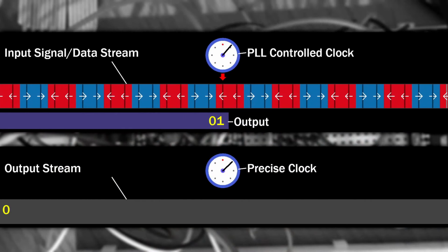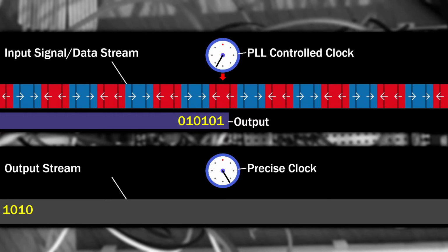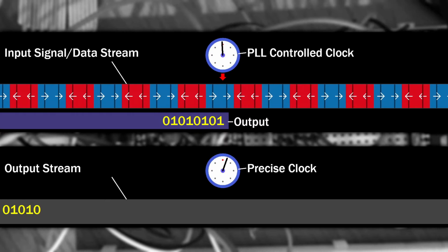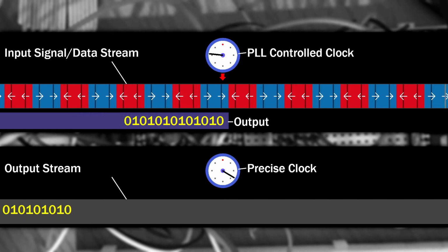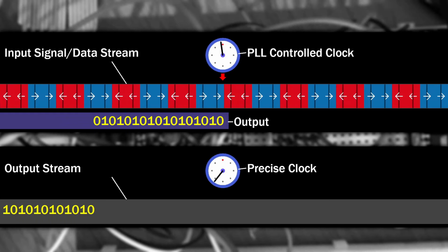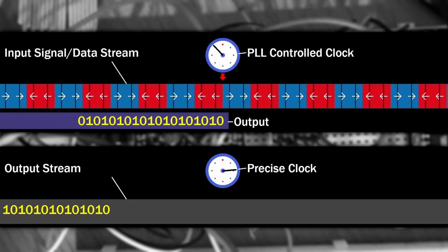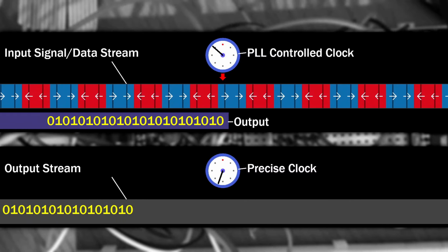First, we need to understand a few things. If you remember from the last video, the drive and various components were able to manage an unstable clock interval from the drive. But when the data is written back again, it's written back at a precise clock interval. Most of the computers of the era could not vary this interval. It was always 2 microseconds for double density disks and 4 microseconds for high density.